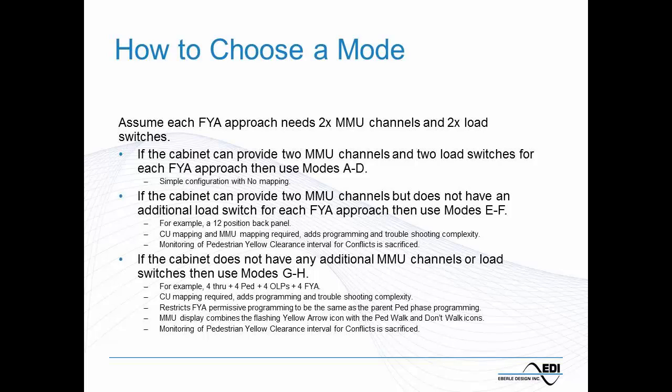It does require controller I/O mapping, so that's going to depend on the capabilities of your controller. Anytime we do controller I/O mapping, that creates complexity for technicians to maintain and replace the controller.